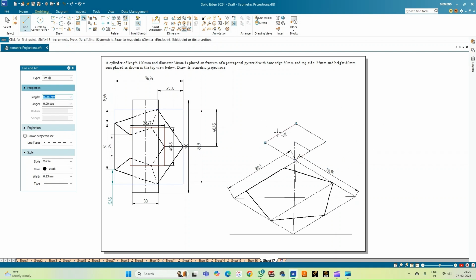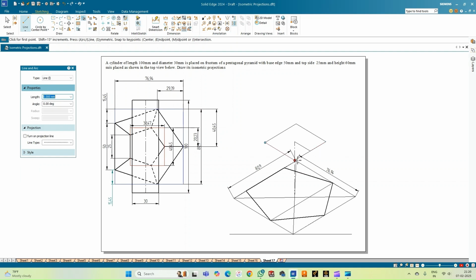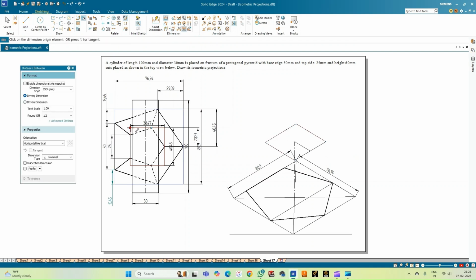So now I need to construct the pentagon here. So let me use the distance between again. So let me consider this smaller rectangle. So it is at 20.23. So let me draw it here. So if I take a line option, 20.23 is here. So approximately the midpoint of this. And similarly, the other 2 points on the longer edge. So this point and this point, it is 7.73. So it will be symmetric here also.